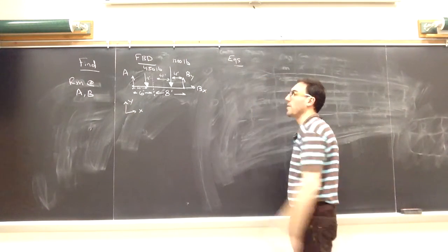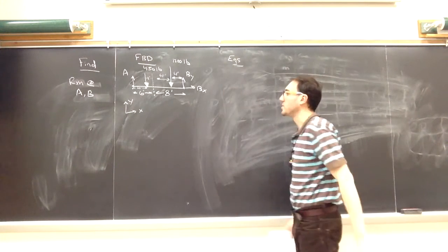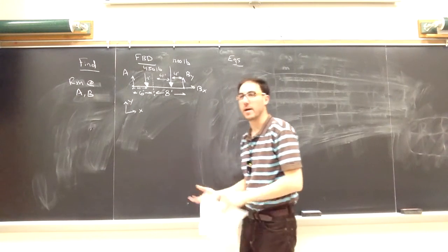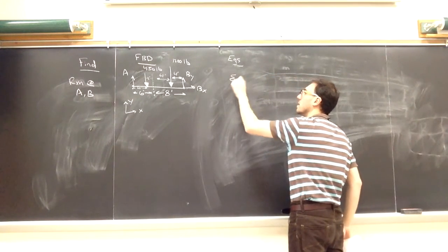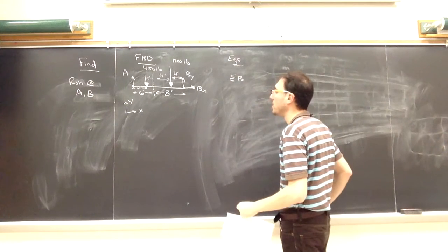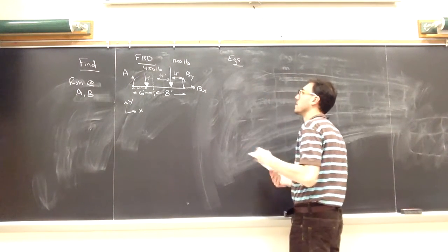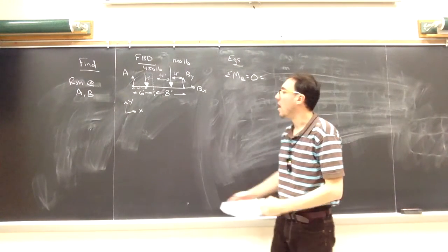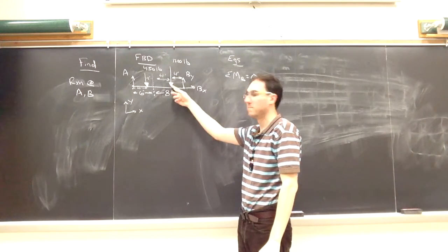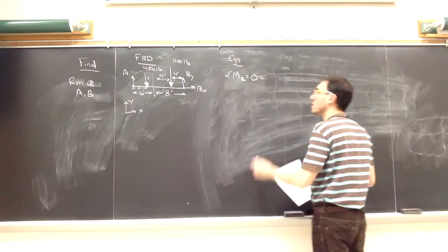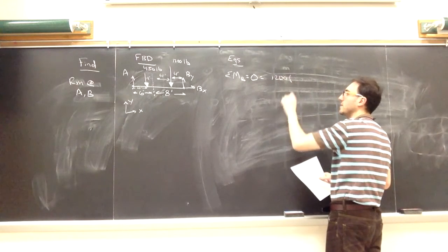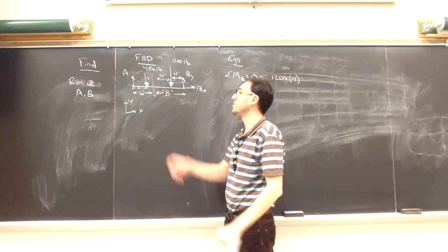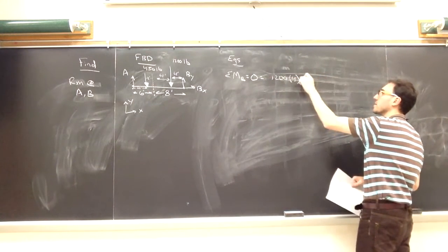Now that it looks like our familiar free body diagram, I can solve for my 3 unknowns, the reactions at A and B, the same way that we've done it in the past. So if I take the sum of moments around B, since we have a pin there, I'll have a moment due to the point load of the rectangular section, and I said that was located 4 feet away from B. I'll have a moment due to the triangular load of 450 pounds.